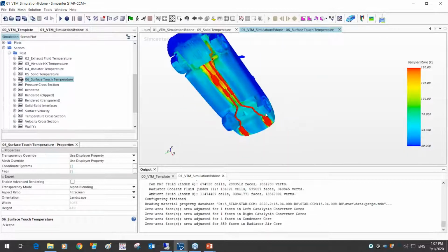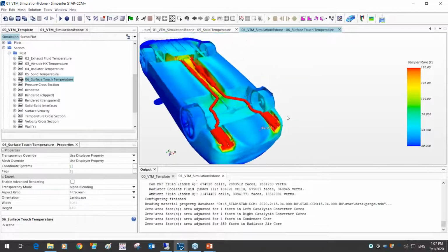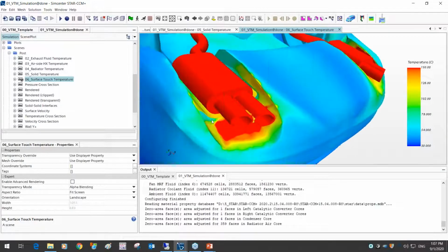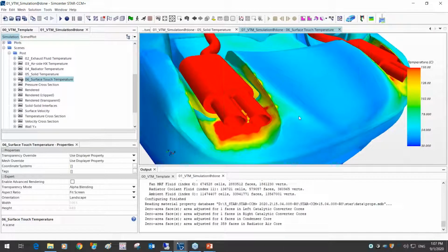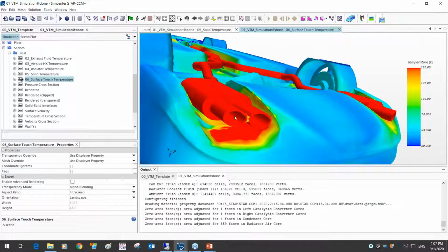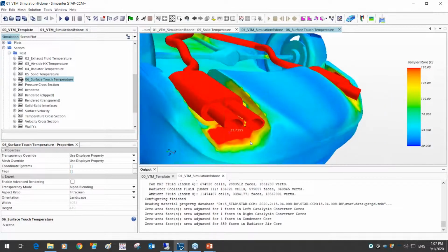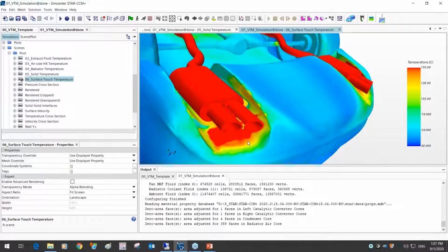You can see on the lower side that this entire exhaust line is hot, and it might grab your attention that the bumper, which is not modeled currently as a solid, is going to be heated significantly by the tailpipe, because the heat shield ends way behind the tailpipe. The critical temperature for a bumper is usually 110 to 120 degrees C, but over here it is way higher.